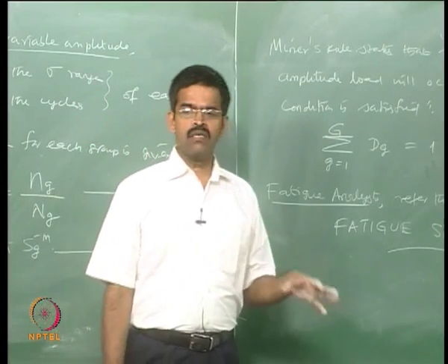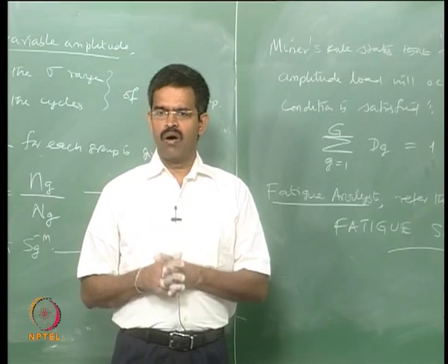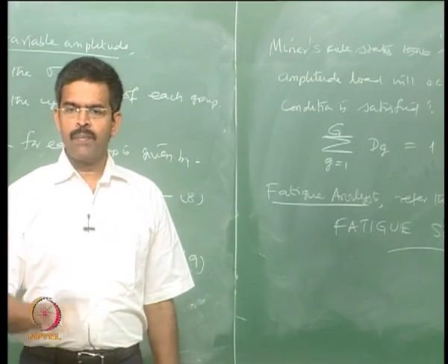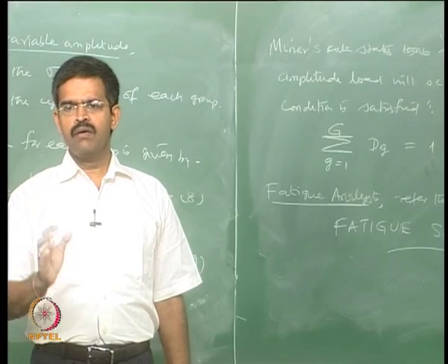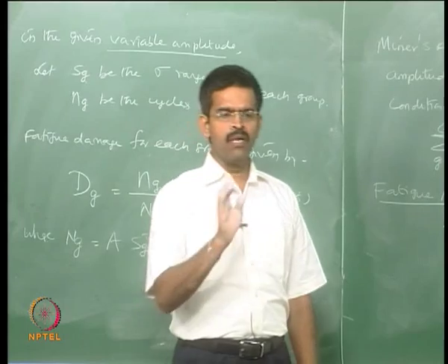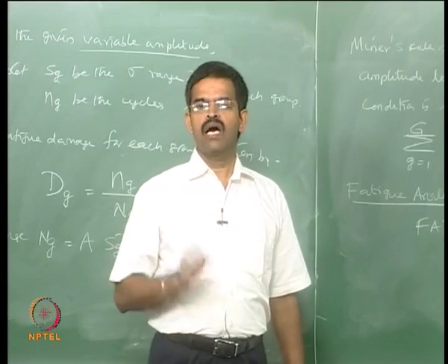But SN curves are done under a controlled environment experimentally on various types of specimens only to estimate the preliminary damage or the preliminary fatigue life of a given member. So, only to estimate the preliminary fatigue life can one use SN curves as a design phenomenon.